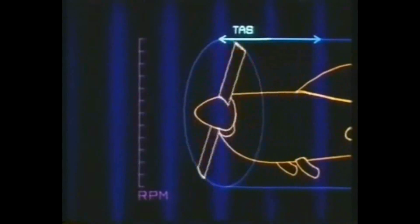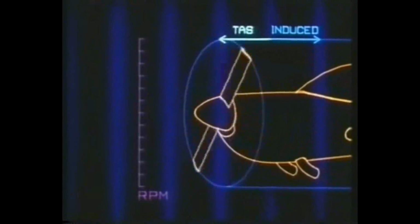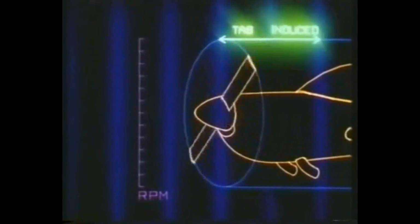With the propeller stationary, any forward velocity is that of the aircraft, the true airspeed. But a rotating propeller accelerates air and produces the induced flow. The sum of the TAS and the induced flow is the total inflow.